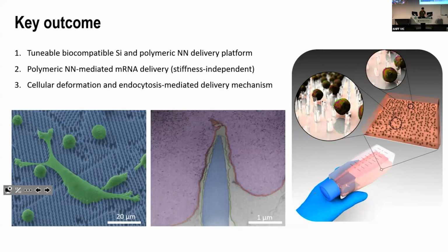What is the needle tip diameter on the silicon, and how is that diameter changed after transferring onto polystyrene needles? The tip diameter is usually less than 100 nanometers in our silicon nanoneedles. With the replication, you will lose slightly on the tip diameter, going to 250 nanometers. So from 100, after replication you lose about 150, but you can always sharpen it if required to get the same kind of sharpness.